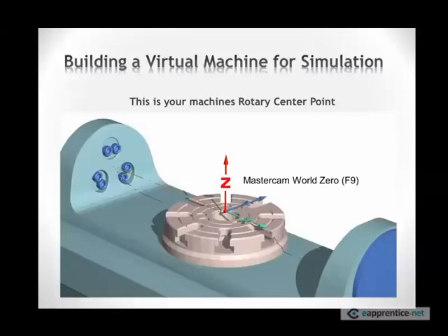And this will change from machine to machine, and this is something that you should do periodically anyway. You should be double checking this number and the fact that your A is 0 periodically, especially after heavy work or, God forbid, a crash. Now, Mastercam 0, World 0, the F9 position in Mastercam, needs to coincide with the intersection of these two rotaries, this point here.